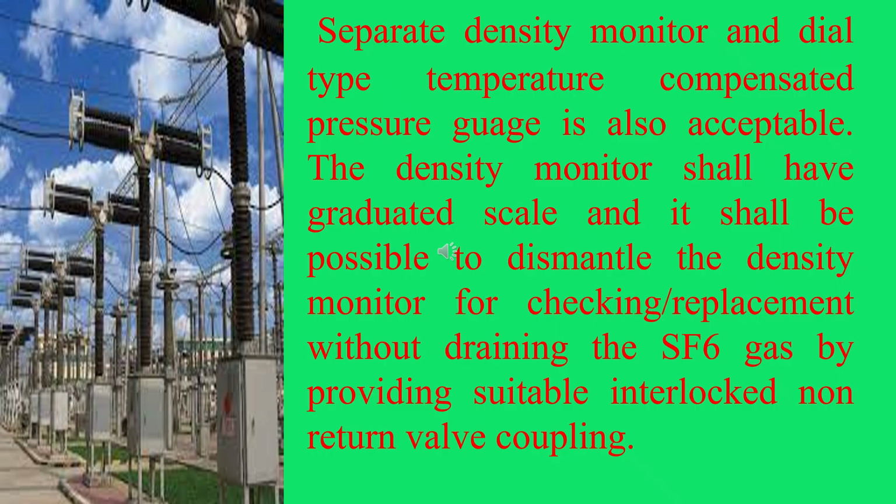The density monitor shall have a graduated scale, and it shall be possible to dismantle the density monitor for checking or replacement without draining the SF6 gas by providing a suitable interlocked non-return valve coupling.